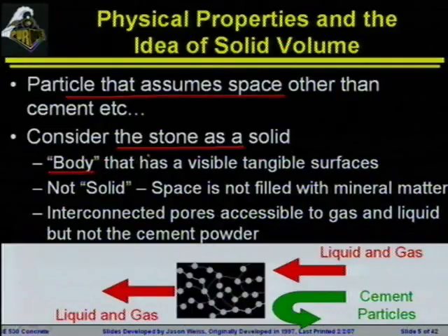So if you were asked to find the outer surface of the aggregate, it'd be pretty easy to find the outer edge. But it's not a complete solid. There is space inside of this aggregate, and it has its own pore structure. So just like the cement paste that we've talked about having its own pore structure, the aggregate has its own pore structure with interconnected pores that are going to be accessible to gas, liquid, but typically not large enough to suck in cement powder or other materials like that.